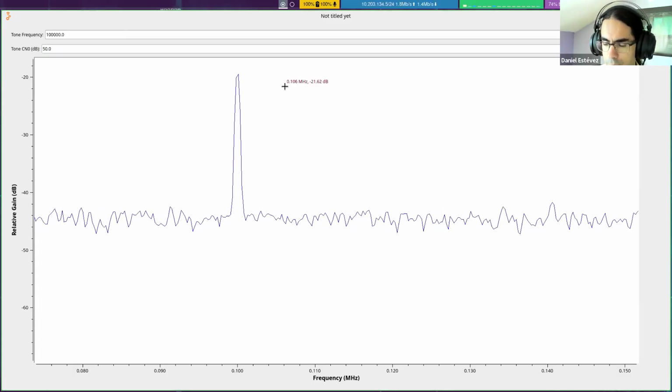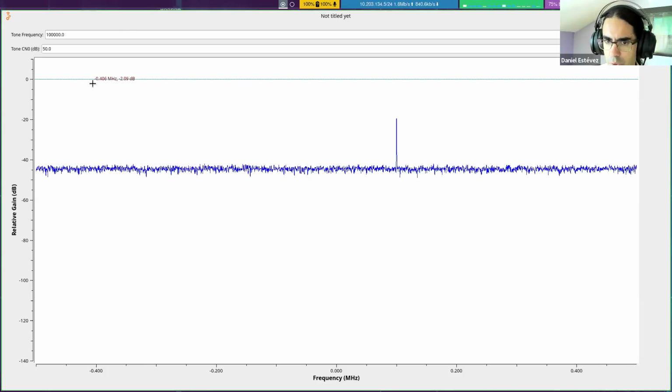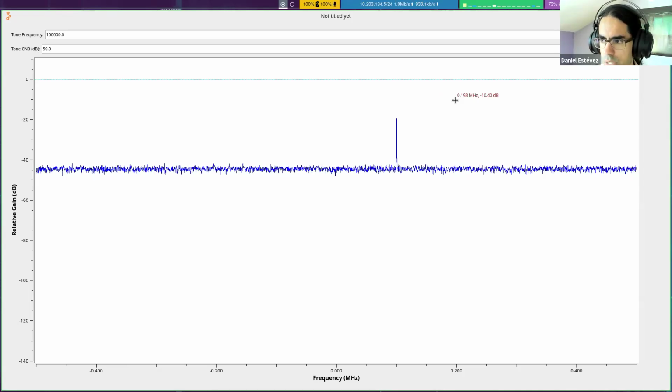That is the thing with this CN0, and these are very useful for measuring signal to noise ratios, because if you tell me I have a signal which has 50 dB CN0, I can already compare it mentally to other types of signals, figure out if it's strong or weak. If you tell me I have something with an SNR of, I don't know, 10 dBs, you need to explain to me which bandwidth you're using to measure the noise and so on. And it's more dependent on your specific setup. Okay, questions about all of these.